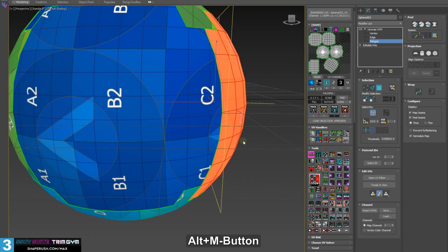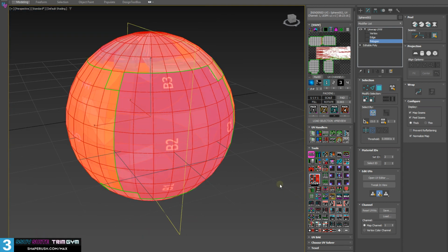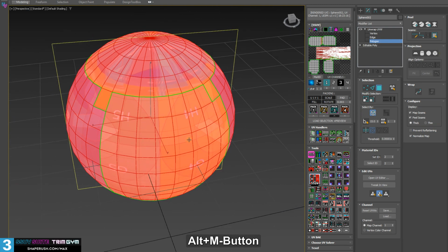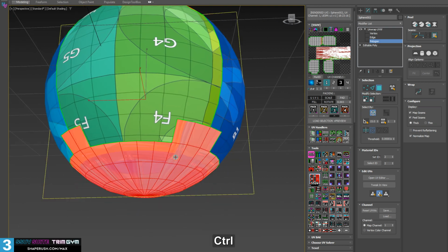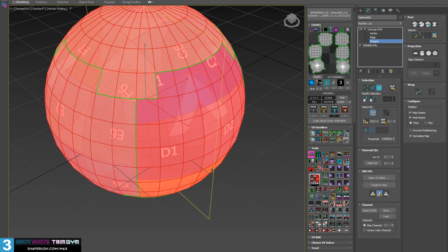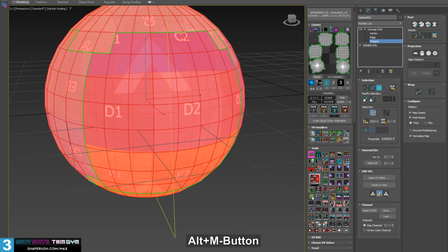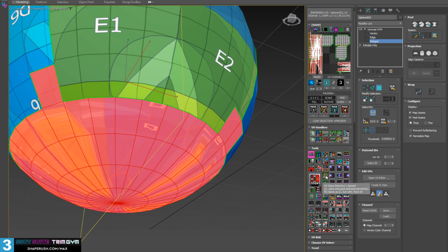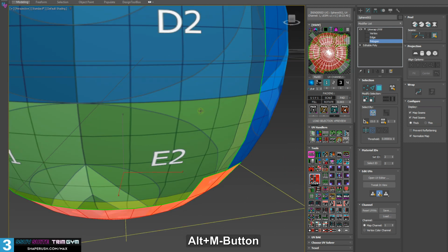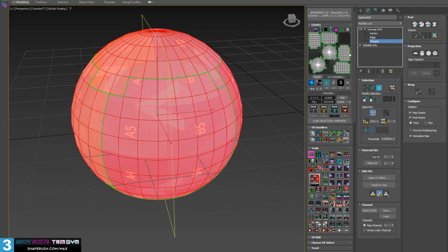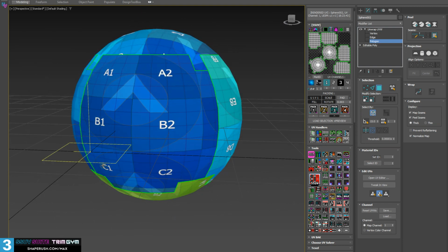And there's that. We can also select the entire object, select straighten, and you'll see that the triangles can't be straightened. So, you know, I don't blame Max. I can't straighten a triangle either. So what we're going to do here is just relax these with a spread. Okay, and I did the wrong spread. I clicked the full spread, so we're going to go back and straighten again. Select the top and the bottom. We'll click the correct spread button this time. Control A and then pack. Okay, so now we have straightened out sides. And the top is laid out well too. So there you go with that.